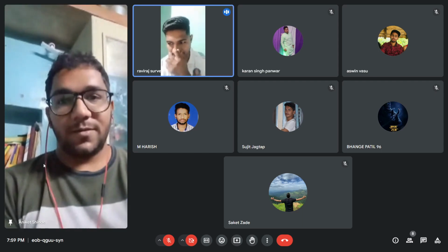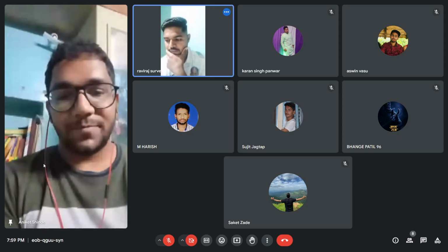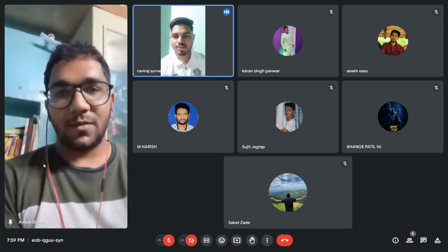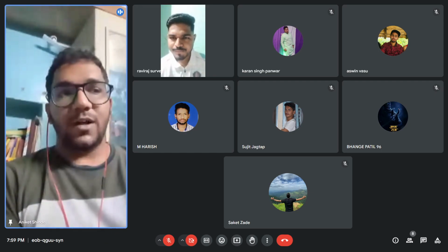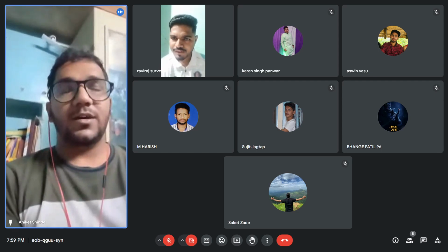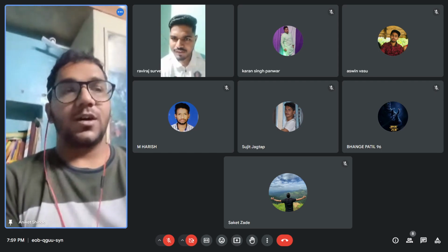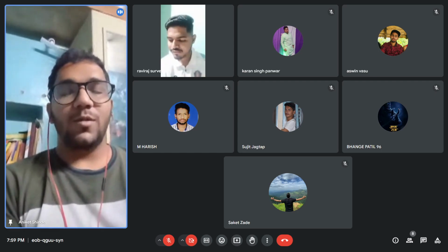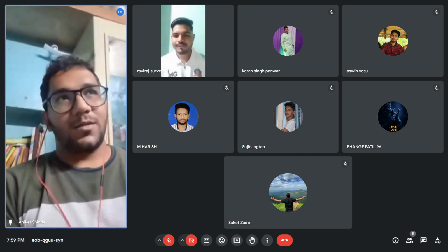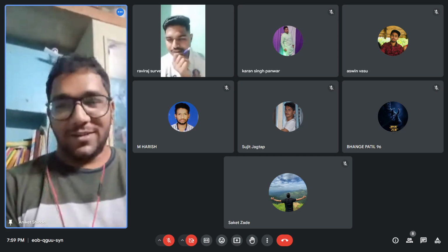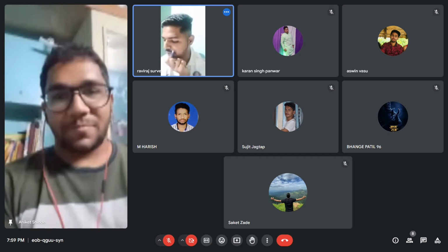Okay. So these are the types of compressor, right? Yeah. Okay. So tell me the names of the safeties of compressor. So first is relief valve or safety valve, and second is bursting disc, a fusible plug, a low lube oil pressure cutout, and yeah, that's all I know.